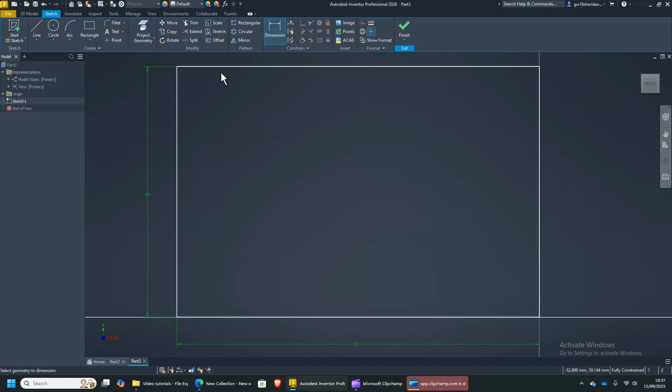Okay, so how can we apply our fillets to this sketch instead? We have a sketch fillet tool up here, so if we click on this and we decide that the first fillet we want is actually 20mm, what that enables us to do is to bring our mouse up to roughly the corner here, and as we approach the corner we can click once and it will trim the curve and put that nice round shape on it.